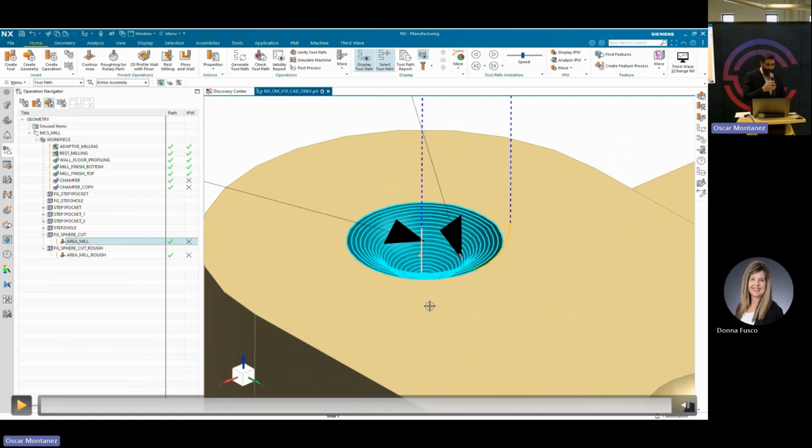So in this demonstration, I chose to use the diameter tolerance, but practically the spacing or the step over is more appropriately associated with the surface finish callout. Because the surface finish callout is a text value, I thought it'd be a good demo to show you how I deal with text values, because that seems to be a little bit more tricky.